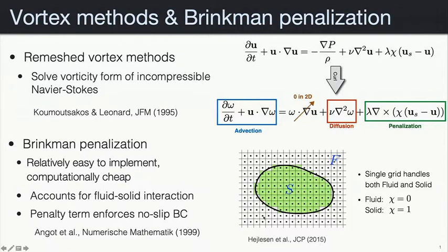And what I'll get inside is 1 meter per second, which is not correct. Yes. So that difference exactly is this term. See, chi is equal to 1, and that 1 meter per second minus 0 will give me some non-zero value. Outside the green cells, everything will be 0, because chi is 0.